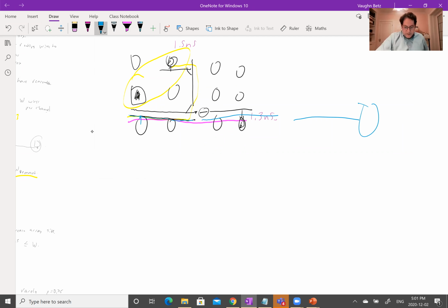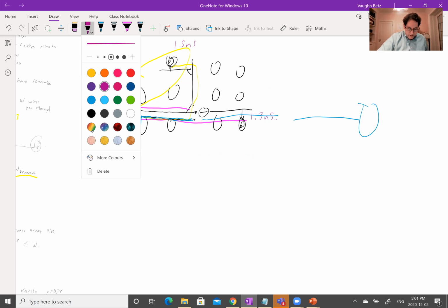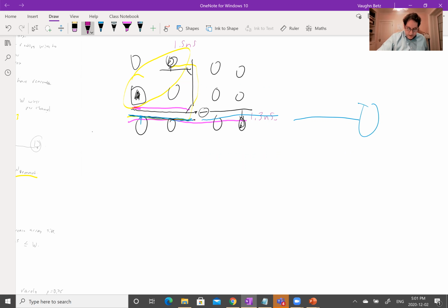Okay. So if this blue routing wire switches at the same time as my clock wire here switches, there is a capacitance in between them. These two wires are beside each other, so there's actually a capacitance between them. And that means if this blue wire rises, it actually makes the purple wire, the clock wire that I've circled here, also tend to rise because it's capacitively coupled. Okay?